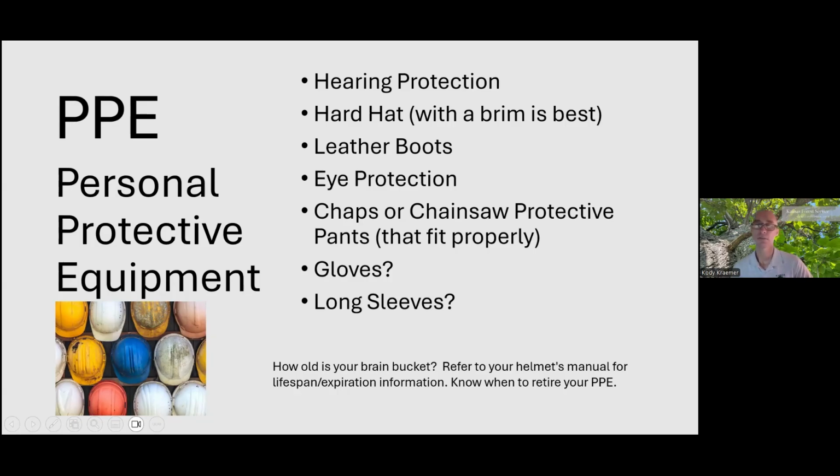A little bit about chaps and pants. All this chainsaw protective clothing that's now available to us doesn't actually protect against a cutting tooth, but it's designed to jam the chain and the drive mechanism. So it's going to stop the chain from spinning altogether. It's not going to prevent an abrasion cut. There are some fibers in all of these materials that are going to quickly get drawn into the saw's drive system and jam up that clutch.